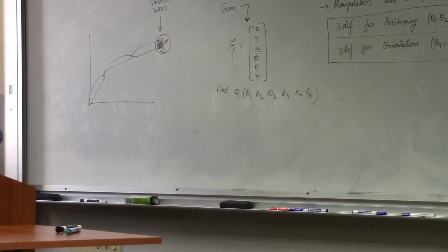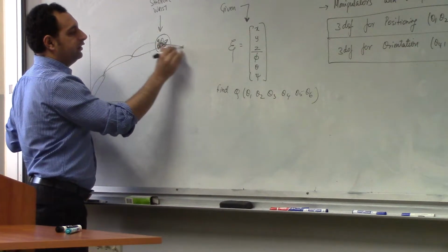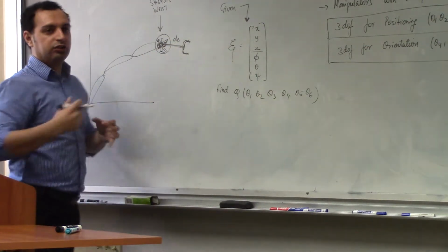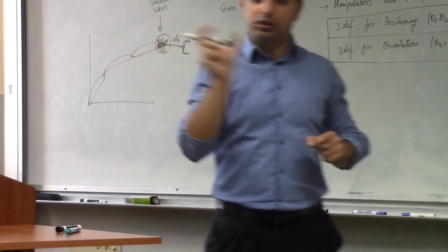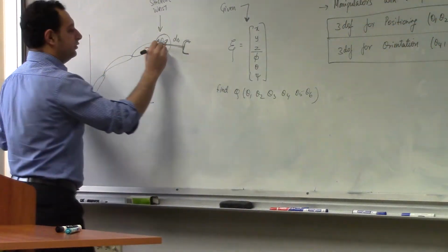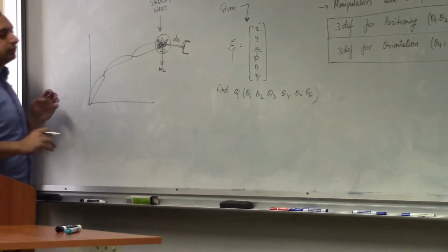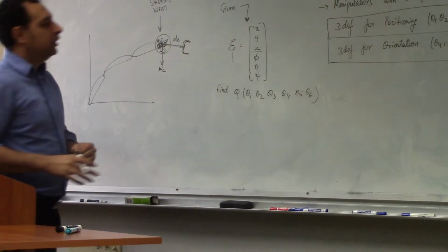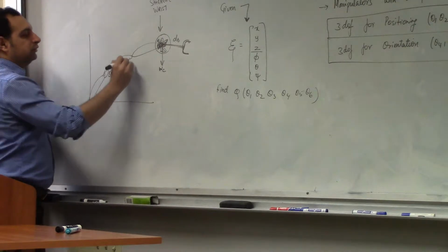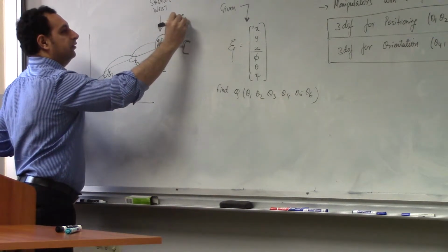If you look at a DH table, wherever you have a spherical wrist, at the end you have an end effector tool length, which is D6. You have written so many DH tables, at the end you have a short length, which is the tool length, D6. Okay, so this is the spherical wrist. Let's call this point WC, or the wrist center. Now, this is θ1, here θ2, let's call this θ3. In this you will have θ4, θ5, θ6.